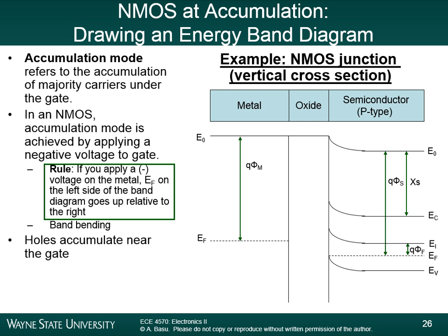Well, let me rephrase the question. What happens when we increase the doping of a semiconductor? Which direction does the Fermi level move? P-type doping? In a p-type semiconductor, yeah. It moves towards the valence band. That's right. When you increase the doping, when you increase the carrier concentration, the Fermi level moves towards the valence band, if we're talking about a p-type semiconductor. So the closer the Fermi level is to the valence band, the more holes you have.